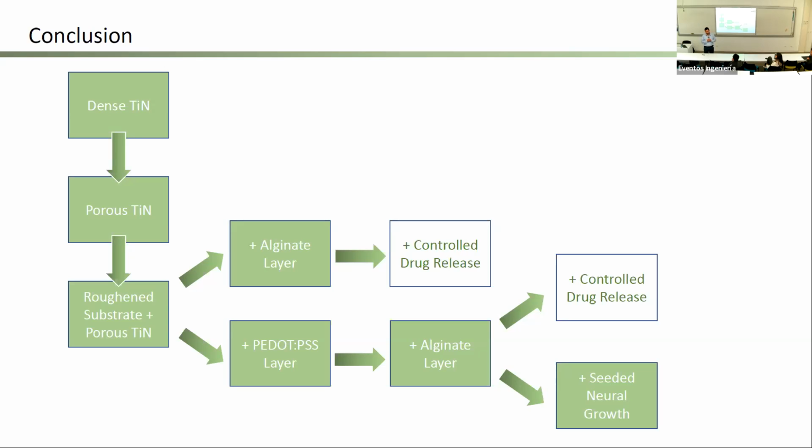And especially from the aspect of the materials, they are very clean materials. So the aspect of having cracks nucleating inside the bulk, I won't foresee fatigue at the surface being a major problem.